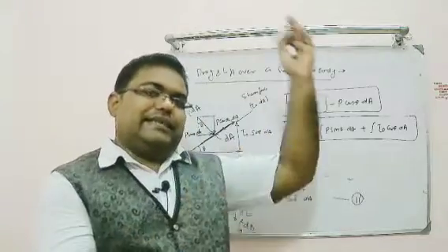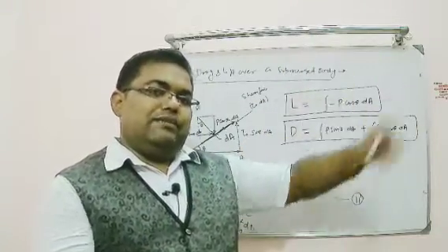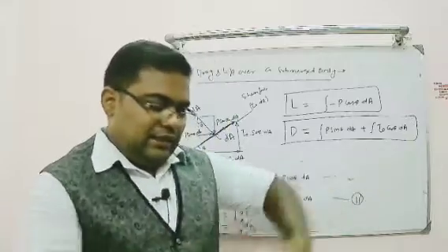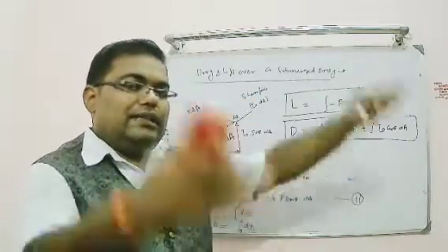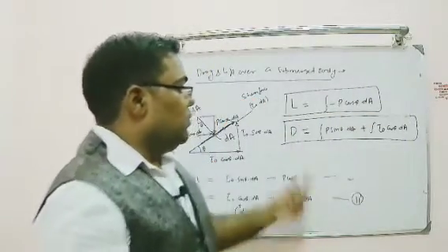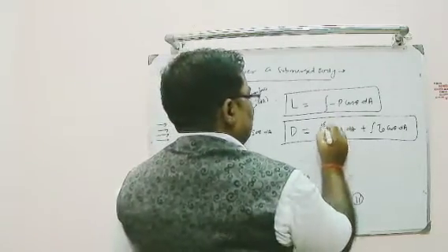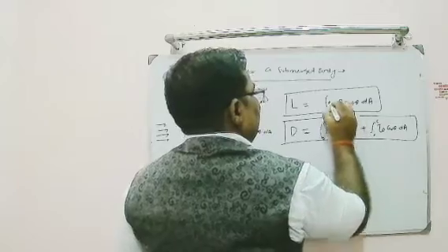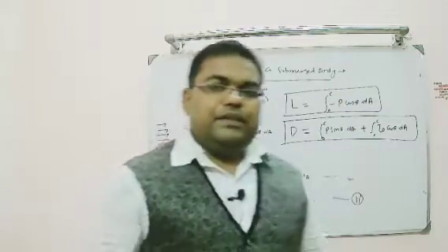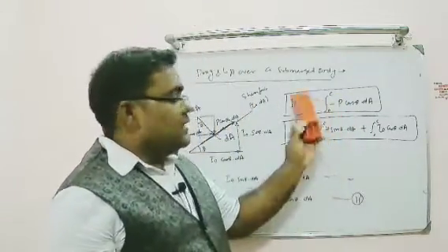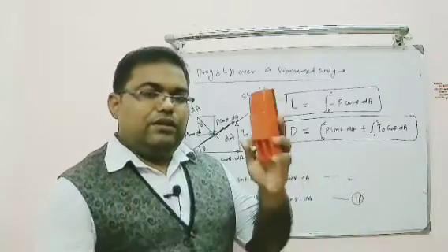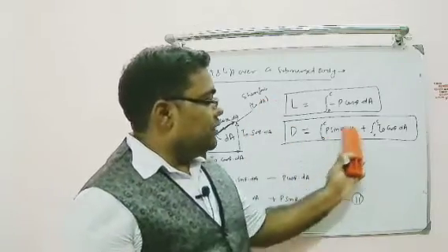So along the thickness, what is the pressure distribution that we will consider? We go along the thickness, then along the chord length, and finally we summarize. When you are integrating along the thickness and chord length, you just mention 0 to C everywhere, and you will finally get lift and drag. So lift is clear: lift is due to pressure difference perpendicular to the flow direction. Now drag, we have two components.